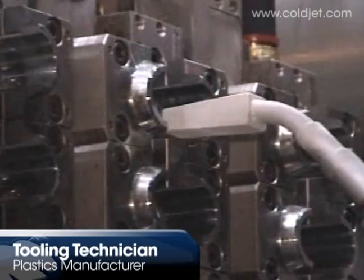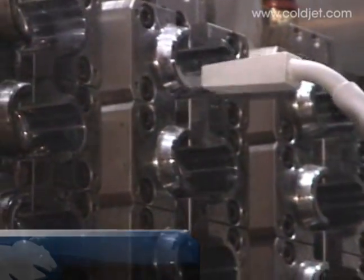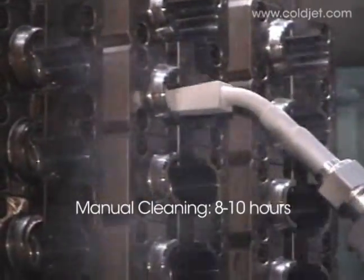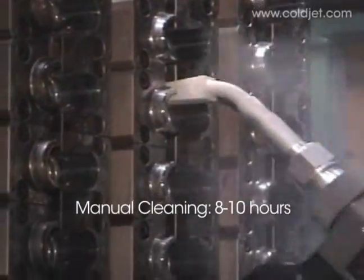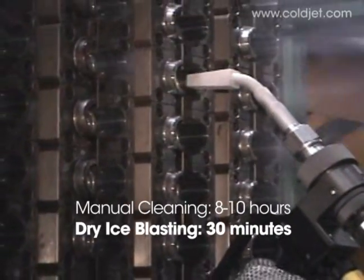Before, due to the dismantling and the extensive cleaning that we had to do, it would take us up to 8-10 hours to do a tool. With the ice blaster, we can do a mold in 30 minutes, 35 minutes completely.